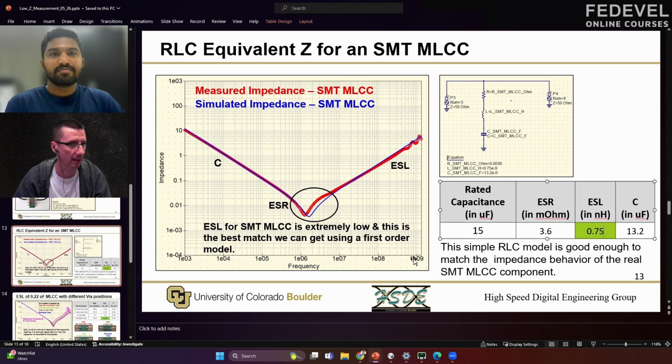What do you have on the next slide? Yes, interesting stuff. Now that we have measured a capacitor, plotted its impedance profile and analyzed it, let's move to another factor which will affect the impedance at higher frequencies. We already saw how the footprint affected the ESL value and in turn affected the impedance at higher frequencies. We're going to look at another factor now.